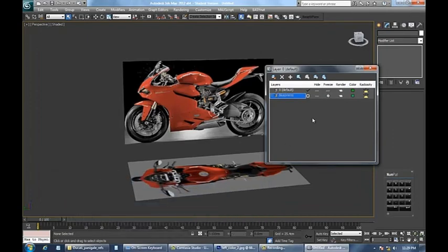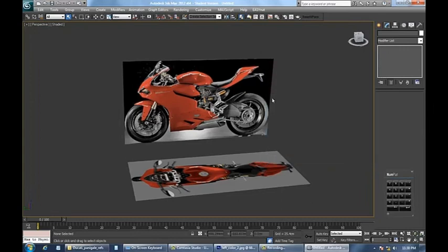Okay, so now they're called Blueprints, and the default layer is the layer that I've chosen with the check mark, because that's the operational layer. If I chose this and went to make a part, then I wouldn't be able to manipulate it, because I'm on the layer with the Blueprints. I'm going to be making parts on the default layer. So I'm going to switch it back over to the default layer, then close it.